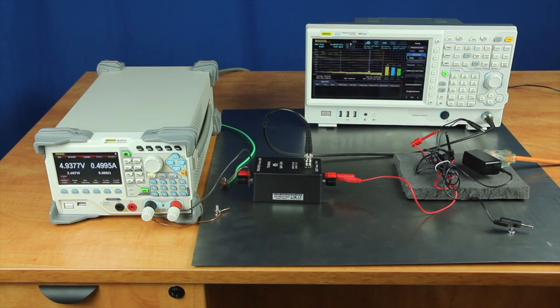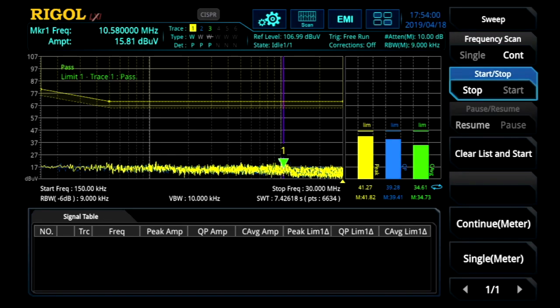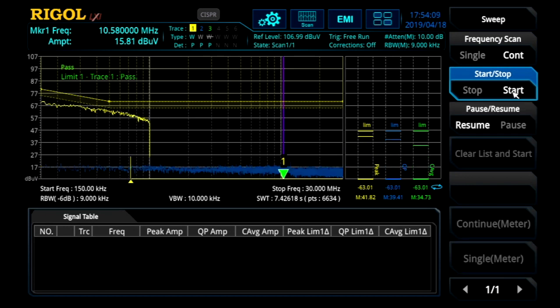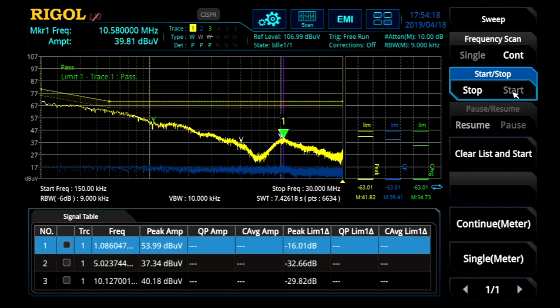In this case, when we go over to the spectrum analyzer, what we see is, well, obviously we have a limit line set up and a margin and our background test. And here you can see that's a peak. Now, if we go ahead and run that test, we see a very different looking sort of emissions set from our conducted emission. You can see on the DC side, near DC side, we have some relatively high emissions coming out of this switching power supply, up near 60 dB microvolts.